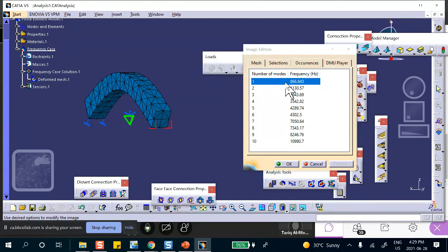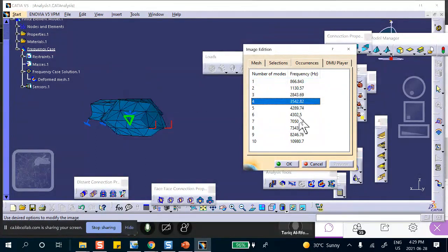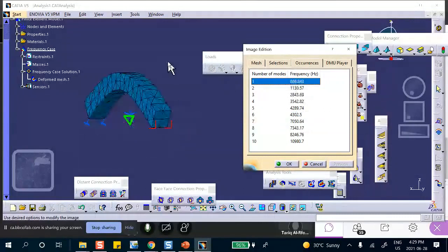If there was a perfect balance, then of course the fan would not do anything. But the fan does not have a perfect balance, and therefore it causes a tiny little bit of force vertically up and down at that frequency. Don't you think that's going to be dangerous? Because if this starts to vibrate up and down, it will never even get to these higher frequencies. It will fail right at that frequency if this was an ideal world. Agree?